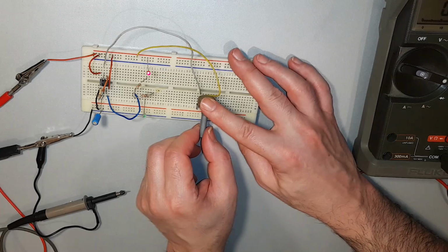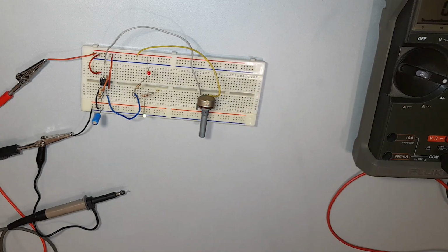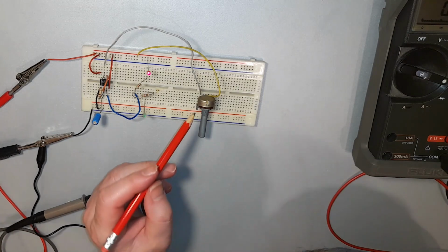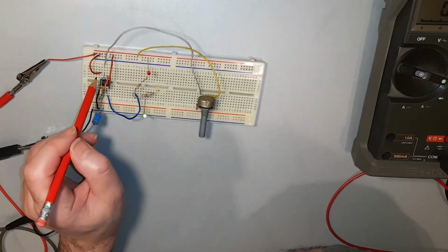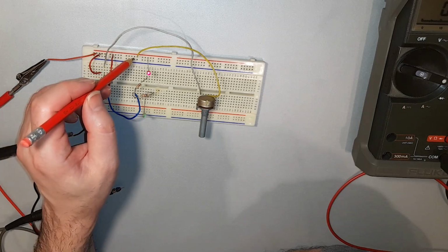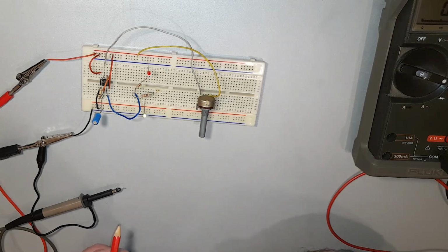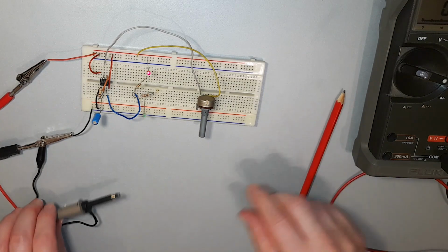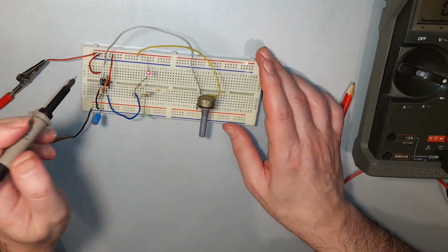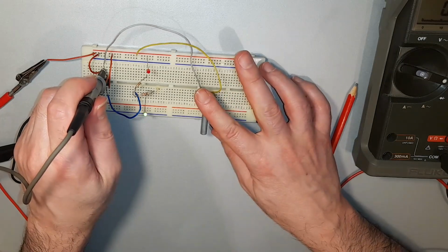So we had a short circuit current flowing straight from positive to pin 7. So you can't do that. You have to have a resistor there, and that's why it was getting quite steamy in there.